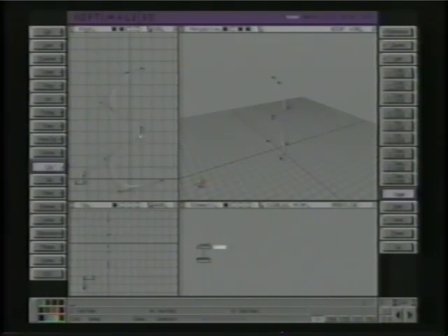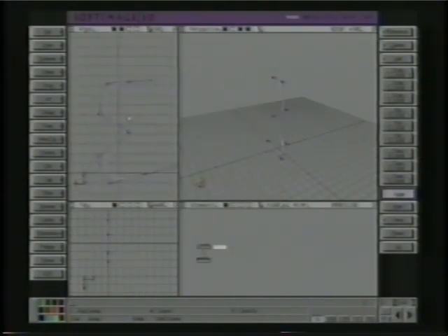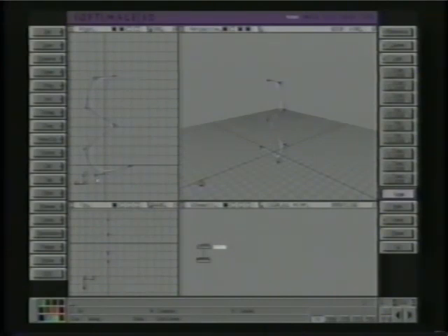B-splines actually have a few advantages over NURBS. They fit tighter to the control mesh, which makes it a little bit easier to see the points. Also, they have what are called phantom points, phantom keys, and when they're in the curve mode you can't see them unless you turn that off. This becomes important later on when you want to artificially join curves or surfaces, most likely surfaces, together, and you can magnet the end points onto other objects and it looks like they're continuously joined. So if you want to make a hard edge in B-spline, what you just do is bring at least 2 points together.